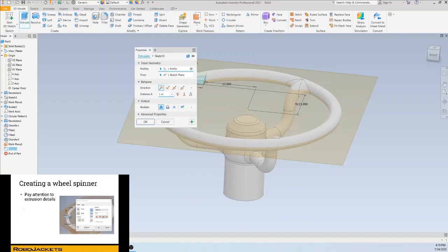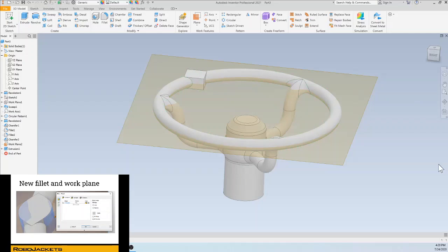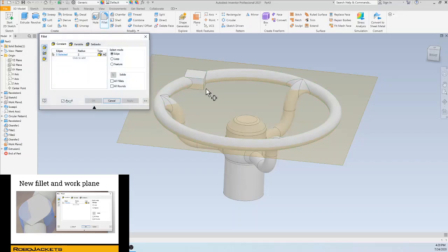But on this, if you look closely, we're not using one direction or even the reverse direction. We're using a symmetric. So it's going to be doing 1 inch total. So it's a 1/2 inch up and 1/2 inch down, but actually we'll be doing 3. The last option would be an asymmetric, but in both directions, so I can choose how many inches in either direction. It's very useful. So we're going to be doing now a fillet to round out the square bunch.